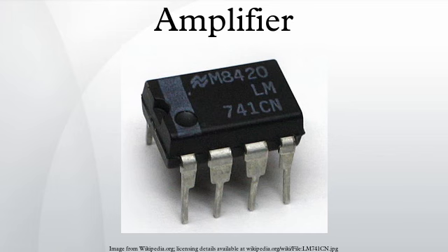In the days of the integrated circuit, a few more transistors on a chip are much cheaper and smaller than a capacitor. Inductive-capacitive coupled amplifier, using a network of inductors and capacitors. This kind of amplifier is most often used in selective radio frequency circuits. Transformer-coupled amplifier, using a transformer to match impedances or to decouple parts of the circuits. Quite often LC-coupled and transformer-coupled amplifiers cannot be distinguished, as a transformer is some kind of inductor.